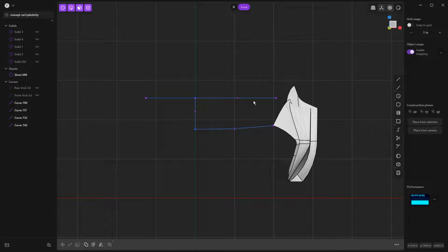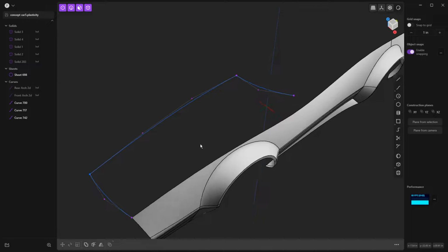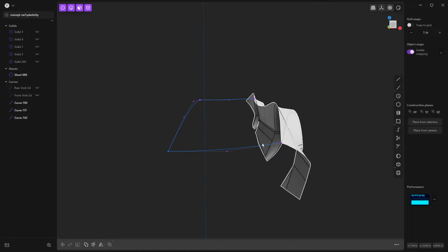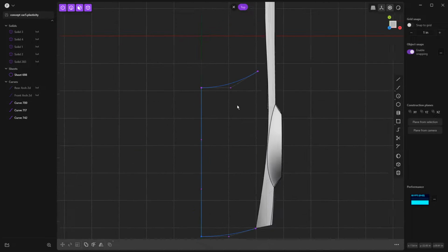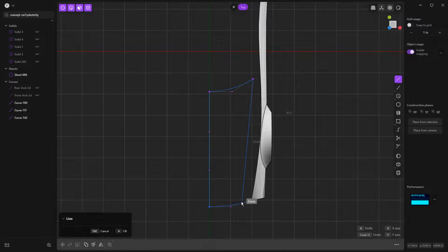In some cases, you'll find that the bottom of windscreens, based on the angle or the geometry of the car, might be completely horizontal. Some might end up coming up a little bit. And so I'll bring that one up. And then what we want to do is figure out where our hood line is going to be. So if this shape is going to flare, actually come back and flare down in, then we want to figure out where that is. I'm going to start that by just drawing a line.